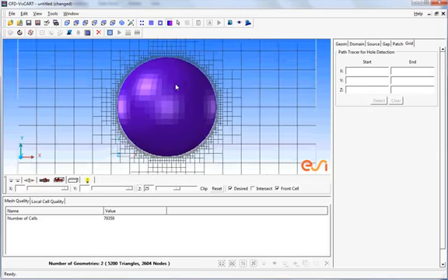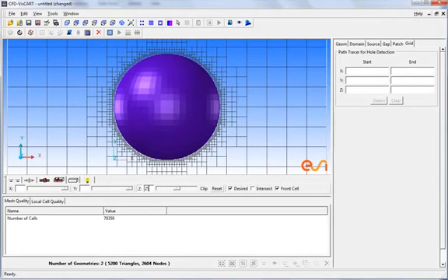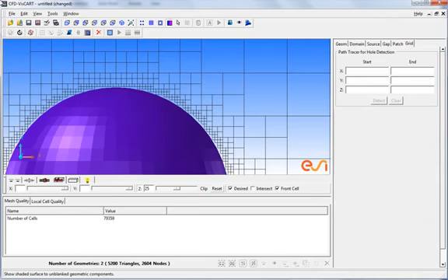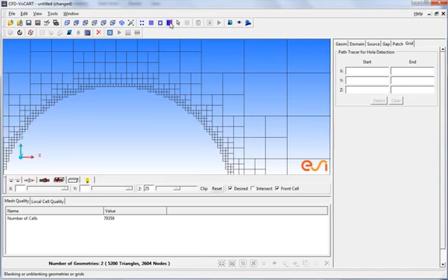The cut plane appears showing the mesh. Zooming in, we can see the jagged or stair-step nature of the mesh. Blanking the geometry surfaces can help better visualize the mesh on the cut plane. Using options in the Geometry and Grid Blanking tab, the jagged surface mesh can also be viewed.